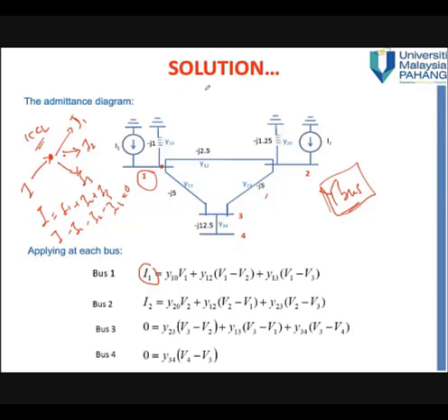If you remember our well-known Ohm's law, your current I equals to what? V equals I Z, right? So your I equals V over Z. And you remember that 1 over Z is what? 1 over Z is Y. So that's why to calculate this current,